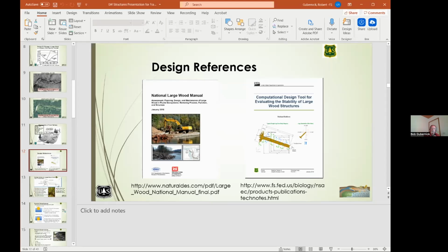If you're using small structures that you saw on the hand, those are mostly all logs themselves and can be used. Typically, when I'm building these types of structures, I'm using 30 to 50% of trees with root fans attached. Some people are concerned about taking the roots out, but we shake all the dirt out. We put the slash and other things from tops that we may not use or branches that are cut off back on there and scattered, and we have found no deleterious effects so far.